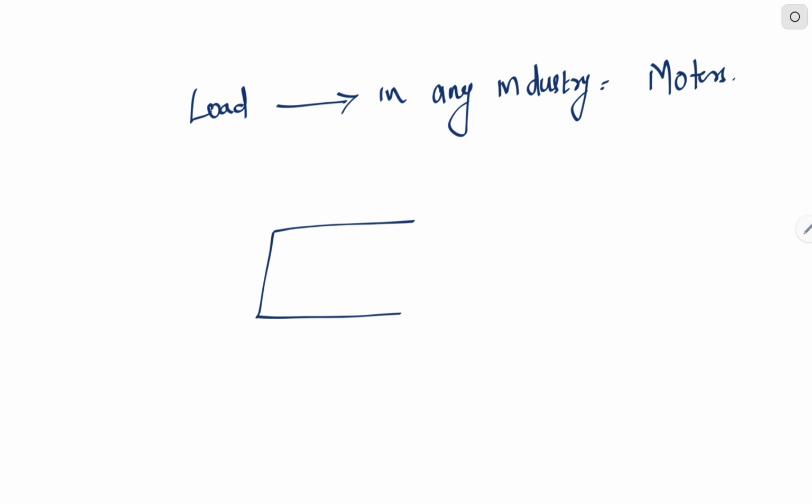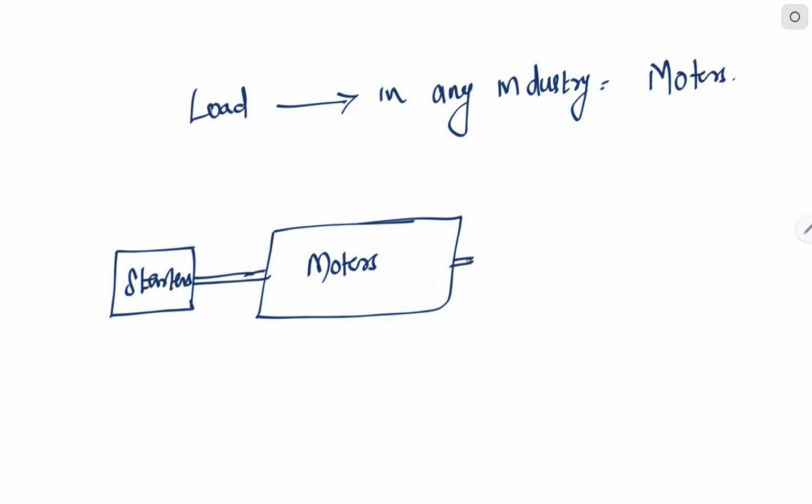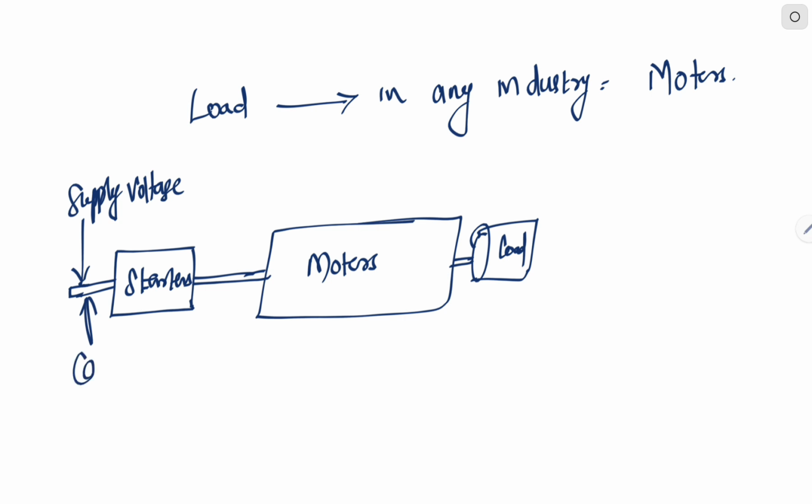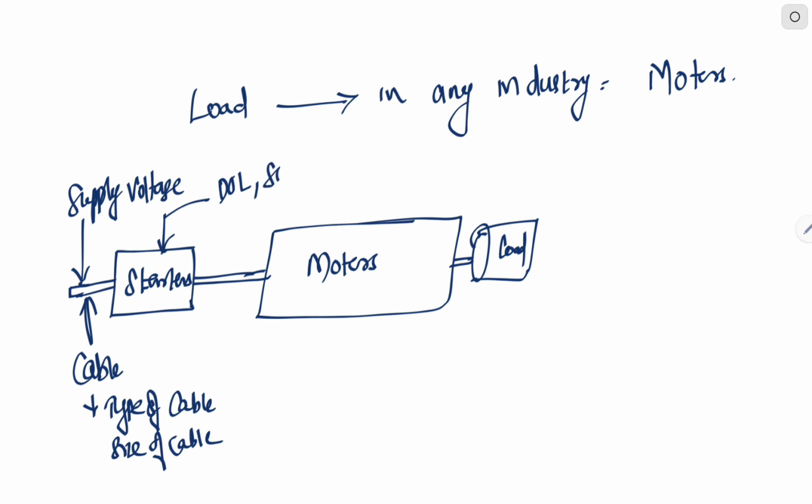For every motor, there will be starters, and for every starter motor mechanism, there will be supply voltage, cable, the type of cable, size of cable, here starter, whether DOL, soft starters or star delta starter, again cable.